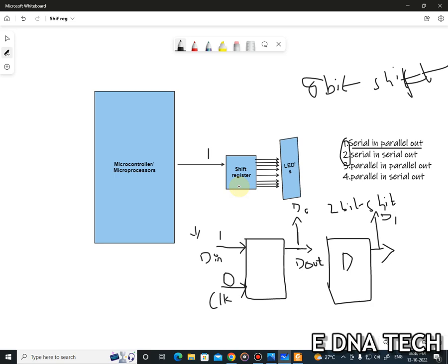Okay, next we are going to see how it is possible to program a shift register with the help of an Arduino UNO. To know what shift registers are, we need some shift register modules. If you search through Google, you can find many shift registers available. Basically the serial in, parallel out shift register is the 74HC595.